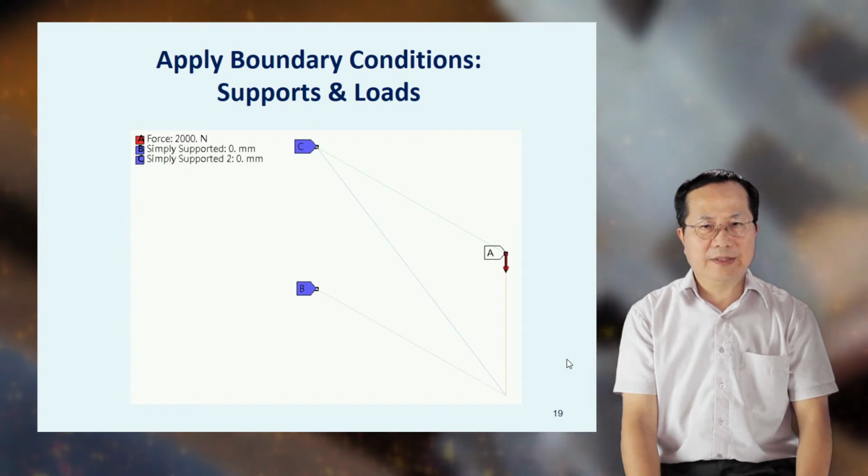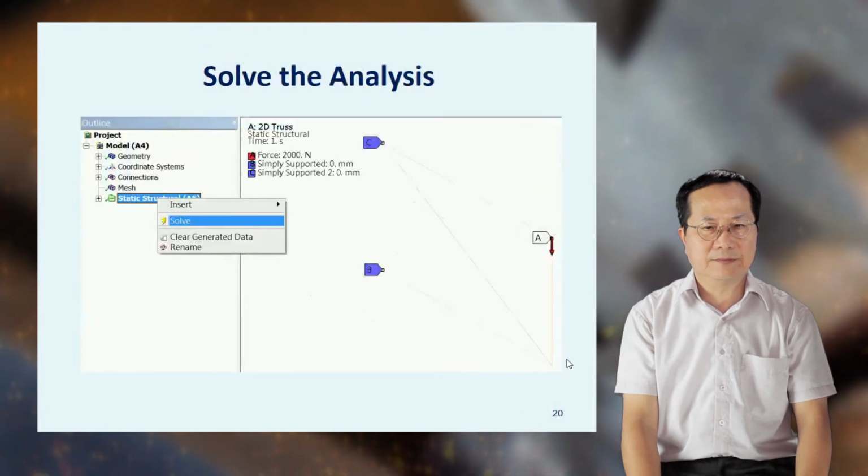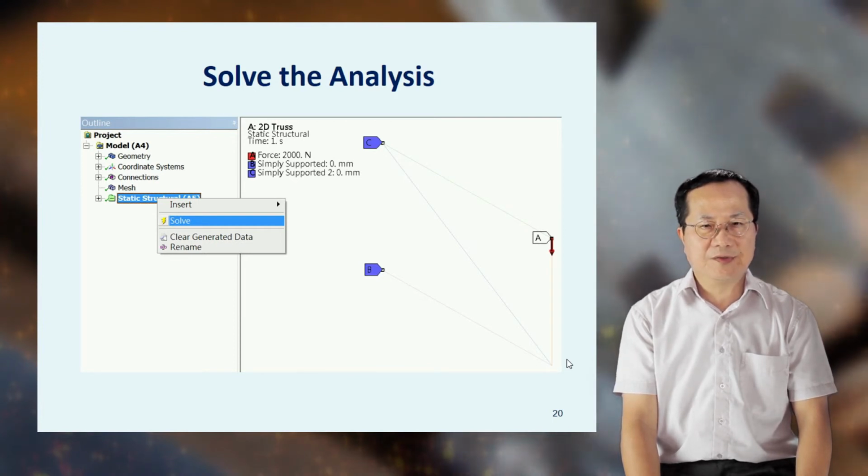In the model tree, select Solution to set up the desired quantities, including total deformation, directional deformation, stresses, and the force reaction. In the top toolbox, press Solve. After a few seconds, the solving process is completed.